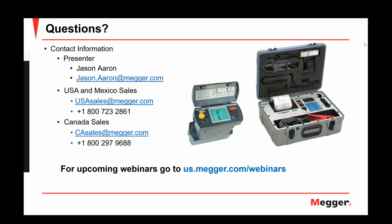The information that you get is going to look very similar to what we looked at whenever we went over the PowerDB form. You're going to have the tables for your impedance values and your cell voltages, and another table for your strap resistances. There's also some other information that we didn't really talk about in our presentation, like a table for temperature and a table for specific gravity in there. We just didn't have time in the scope of our presentation to go over that. So to answer your question, yes, you can use the Megger BITE 2P with PowerDB.